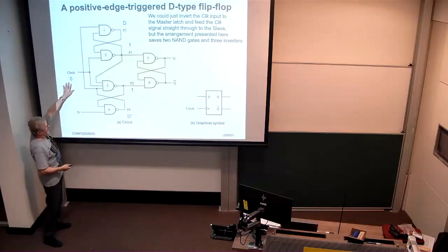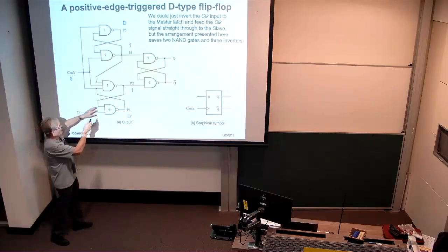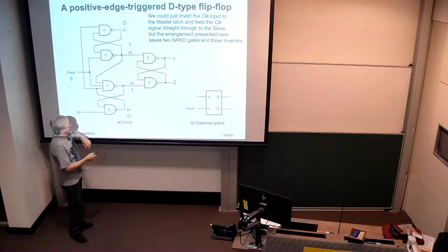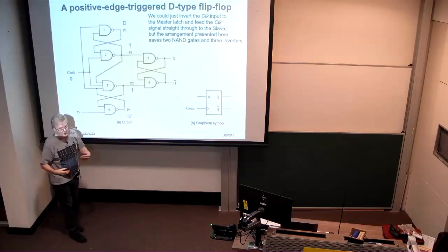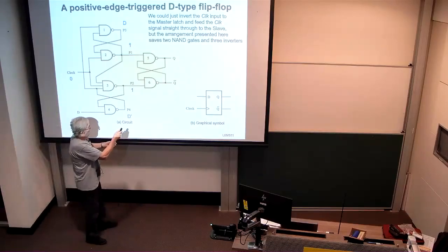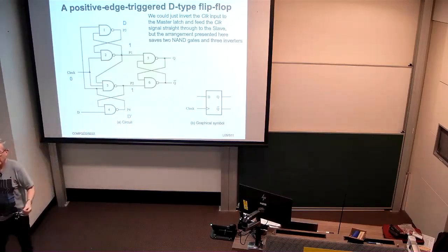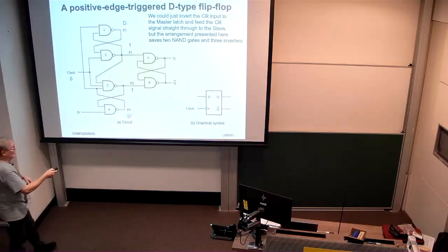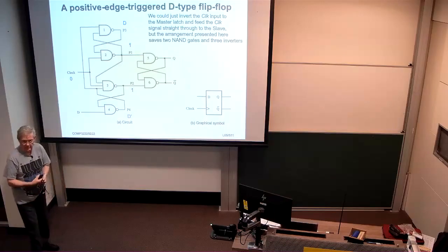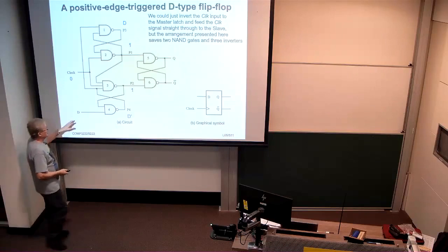So only when one of the inputs is high that it inverts the output. So we see when the clock is low, the outputs of these two NAND gates, 2 and 3, at P1 and P2 are both going to be 1 because the clock's low. As a consequence of that, both NAND gates 5 and 6 have one input that's 1, and therefore it's inverting the other input to the NAND gate, right? So Q and Q bar are reinforced. So far, so good?